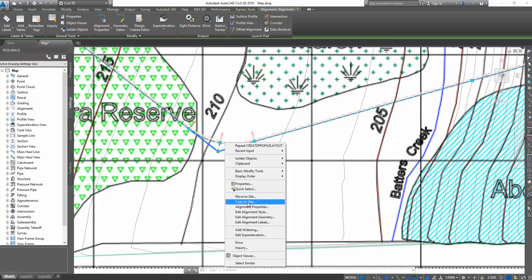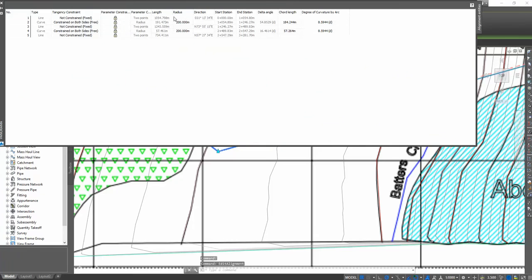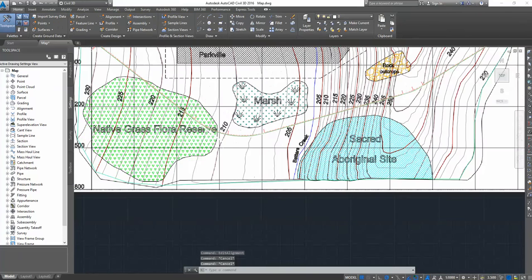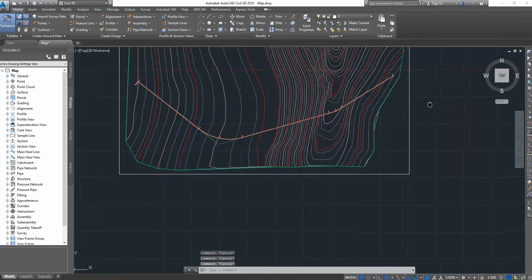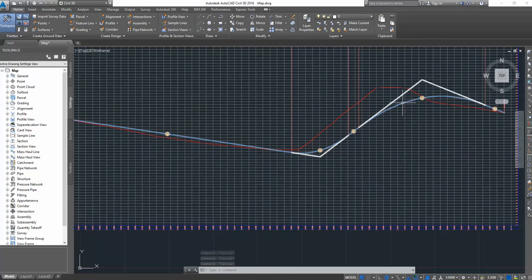These horizontal curves. So you go to your edit alignment geometry, go here, say it's at a radius of that, and let's add a design speed of 110. You need it to be 550 meters. I'm going to change this one to about 550 as well. Then close this, escape. Now when you come, this has all been changed.